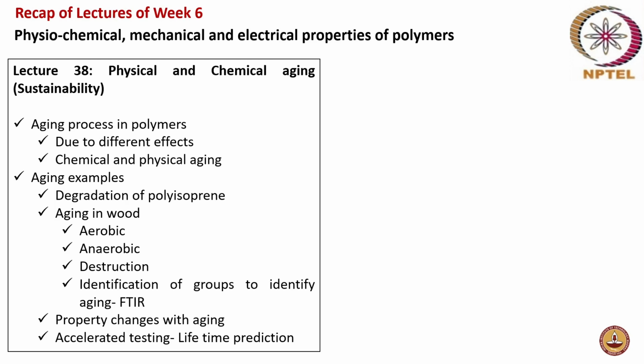And then how the properties change with aging. For example, there was an example cited like a gasket. So a gasket becomes more stiff, right, over the usage? Or sorry, what happens in the case of a gasket? Do you remember? There's an increase in modulus. It becomes stiffer and there's an increase in modulus, right? Which is not a suitable parameter for its functioning, correct? And at the same time, there can be some other materials where the modulus decreases. The structural component's modulus decreases, which is also a negative aspect in terms of the functionality of the material.